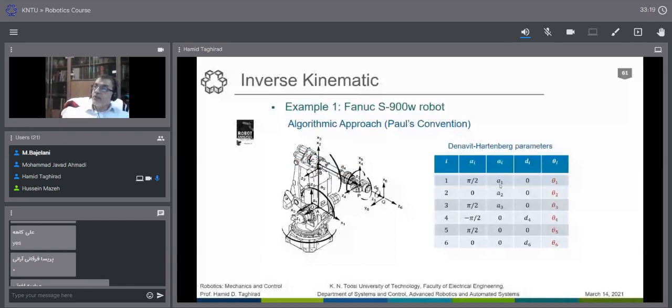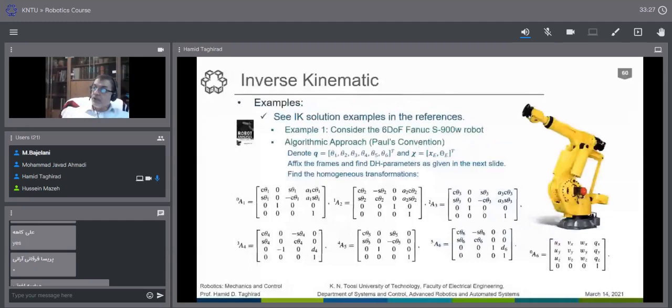The end effector point Q, Qx, Qy, Qz is given, and also its orientation. The orientation is given with a rotation matrix. So this is given basically in the inverse kinematic problem, which we call U, V, W, 3 columns to make them much easier to interpret in the system.